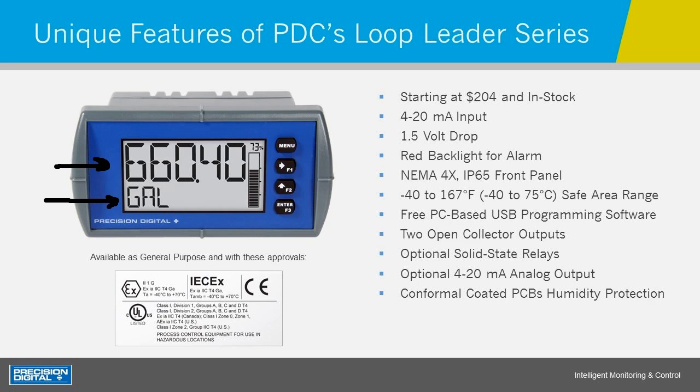We've got a lower display that can show you a unit or tag and has 14 segments on it. So remember, for example, I've got the ability to show this G very clearly with that little notch in the G. And you've seen, for example, how tank looks on a 7-segment display versus a 14-segment display earlier. I've got the ability to see percentage above my bar graph. So I've got both a percentage display and a bar graph display. And so there is just a lot of information that is packed in there.